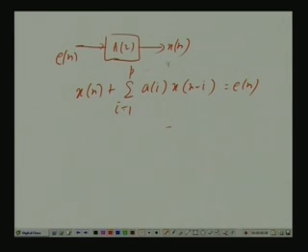You can model this by a filter like this: there is a linear prediction error sequence called e(n), which may not be white, and is white in the case of an AR process. It is passing through a model A(z). What is A(z)? That is the transfer function of this AR system and gives rise to x(n). A(z) is X(z) by E(z). If you take the Z transform of the left hand side and right hand side, obviously you get that all pole transfer function, and that is your A(z).